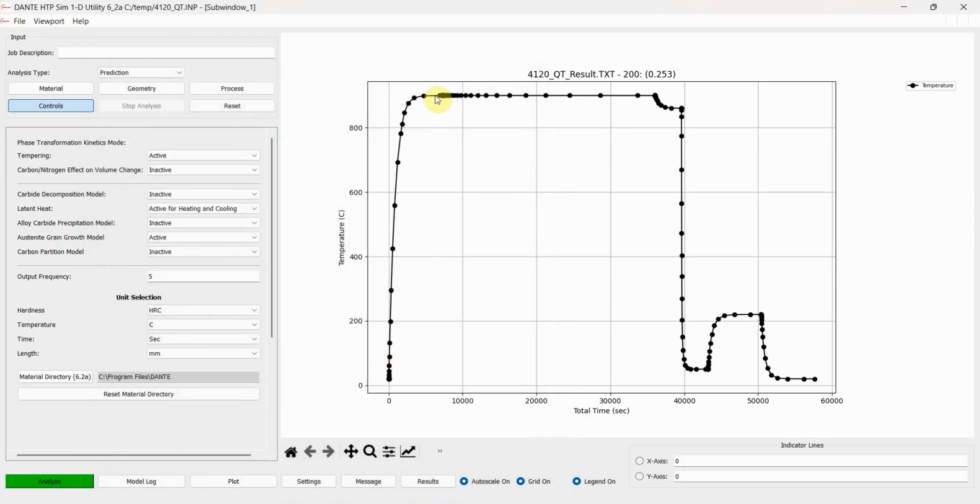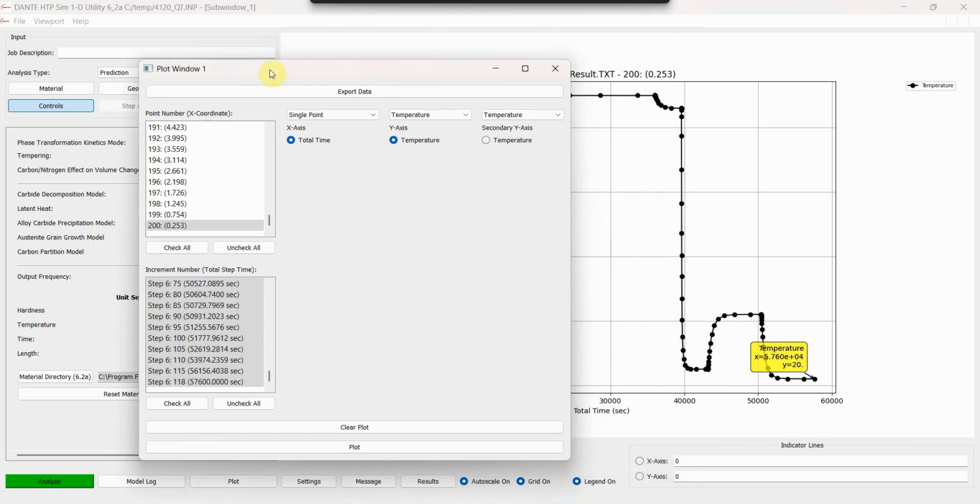And we can see at the end of the heat up process, we are at 900 degrees C. So we have that 20-minute soak after that. And then we have 900 degrees C throughout the carburization process until the ramp down. In the ramp down in temperature, the core does reach 860 degrees. It does quench down to 50 degrees C. And then 220 degrees was our tempering temperature, and 20 degrees C is our ambient cool to room temperature. So the core of the part did achieve the temperatures that we were looking for.